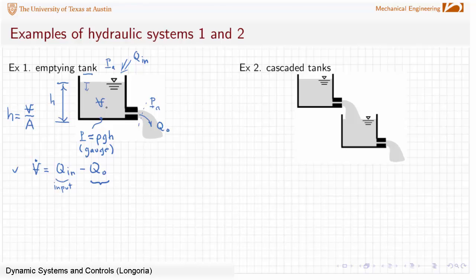We just choose volume. And one of the reasons I like to say we choose volume is because it really is compatible with the dynamic equation that we use, which is the continuity equation, right? It's the rate of change of volume that's the difference in the flows coming in and out of the system, the flow rates, right?